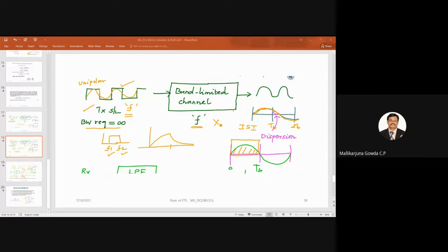So it is based on the number of RC components in the filter. If it is a first order, only one R and C component will be there. To say second order, we will have two RC components. So for a first order low pass filter, the gain reduces at what rate? Minus 20 dB per decade increase in the frequency.